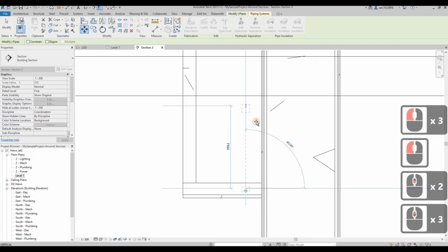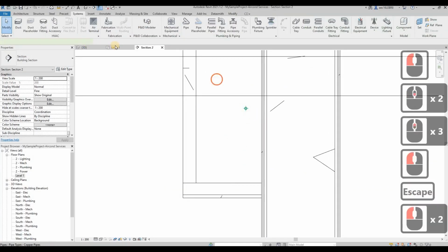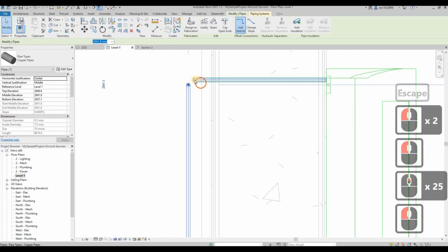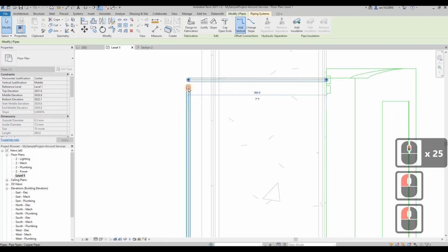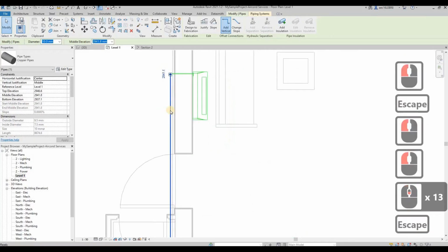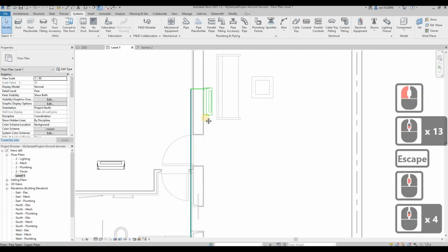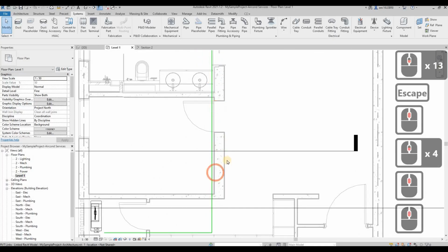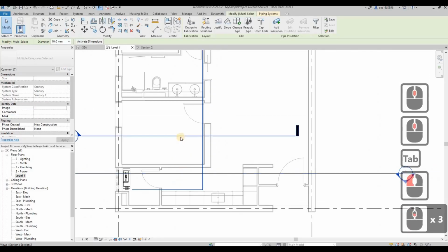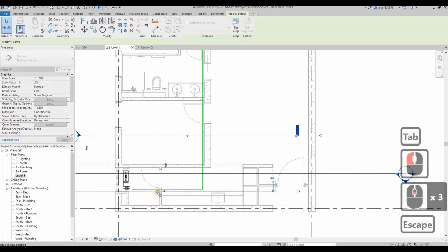Once you adjust, you need to adjust it to the top. Then go back to the plan view. Then you connect these two. Automatically it will form an elbow here. Of course, this consists of two pipes, one supply and one return. You can model two pipes, or you can just leave it as one as indicative.